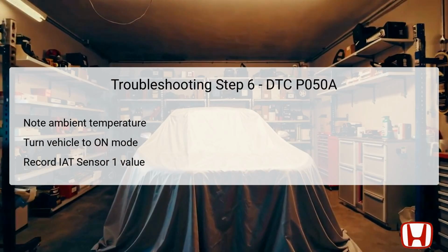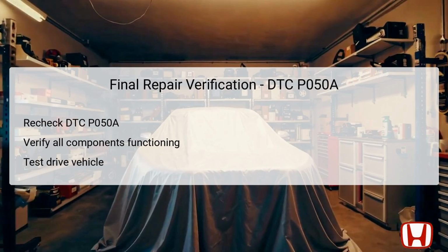A correctly functioning IAT sensor should show a difference of less than 5.4 degrees Fahrenheit or 3 degrees Celsius from the ambient temperature. If any discrepancies surpass this threshold, it indicates a possible malfunction in the MAF or IAT sensor, warranting further investigation and intervention. Once all troubleshooting steps have been executed and rectified, it's essential to recheck for DTC P050A to confirm that the issue has been fully resolved.